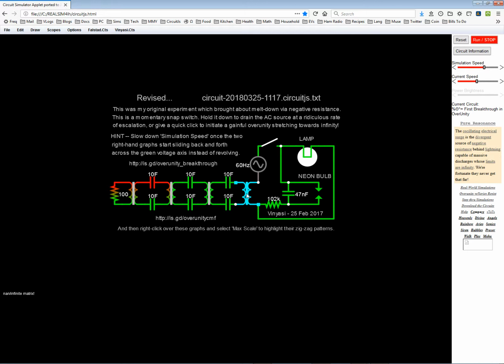So I arbitrarily chose 10 milliohms per capacitor and 4 ohms per Henry per coil or per transformer coil, either kind of coil, or center tap transformer for that matter. And that does a very interesting thing. This particular configuration of caps and coils actually accelerates with the help of equivalent series resistance.